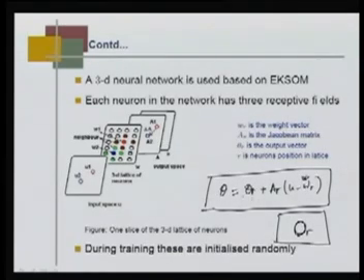And theta, given any point close to this point W r, given any other point u which is close to W r, the corresponding theta is computed by this linear equation. But unfortunately, we do not have the information what is theta r, what is AR, and WR we have learnt using the Kohonen SOM. We know only U, we have to compute what is theta. So, we do not know what is theta and AR, that has to be learnt. So, this is learnt using some feedback mechanism.